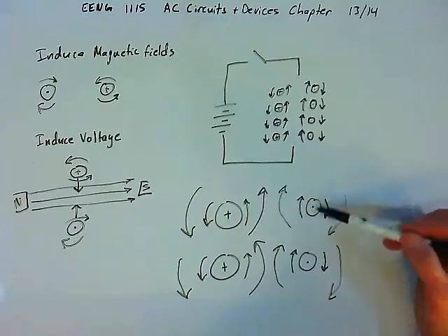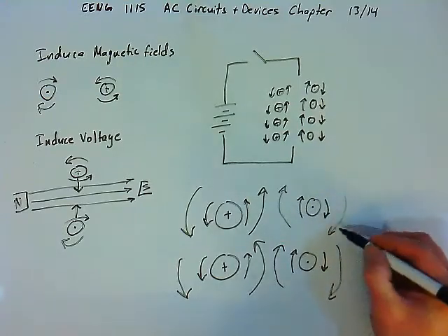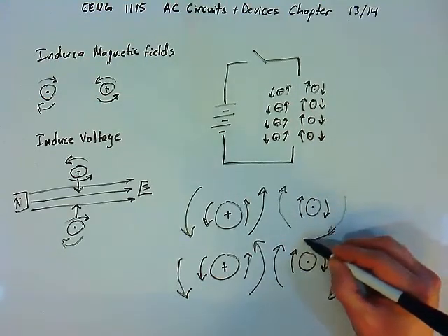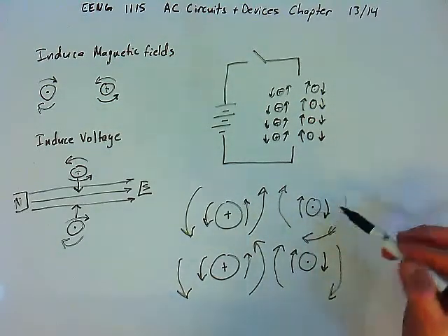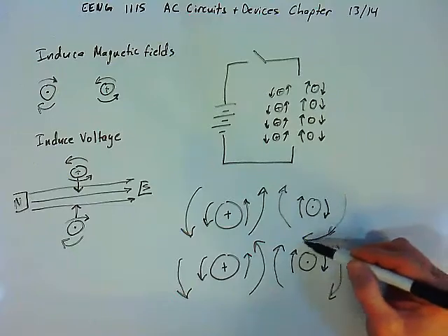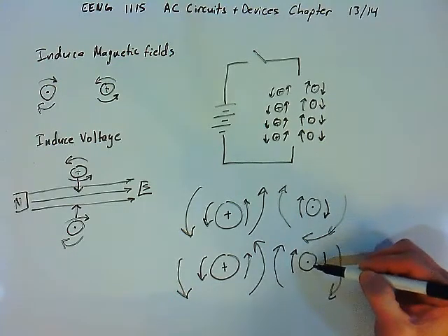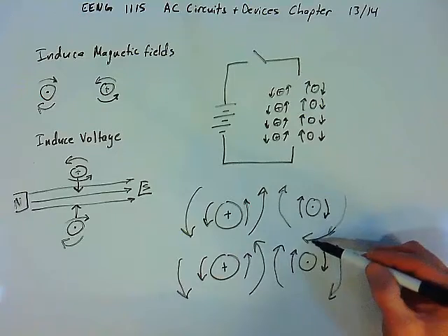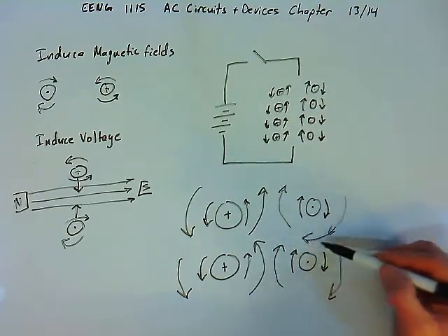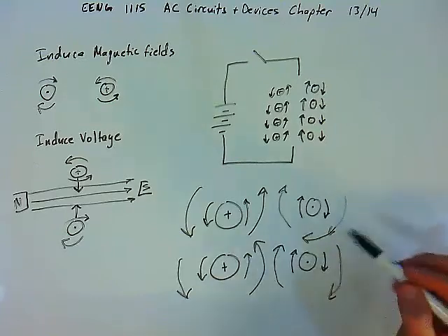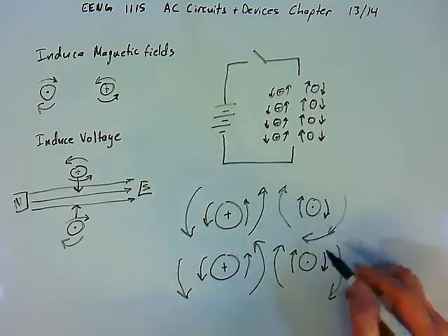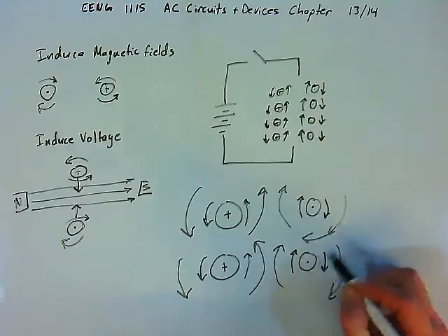And so for these two neighbors, this wire is inducing a magnetic field that is directed clockwise. As that magnetic field continues to grow, this field line is going to grow and cut the neighbor. And so the field line is above the wire, the field line is directed to the left, and it's passing down across this turn, its neighboring turn in the inductor. And so when this field line cuts this conductor,